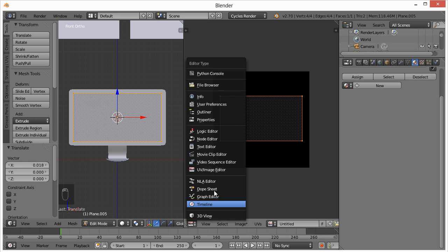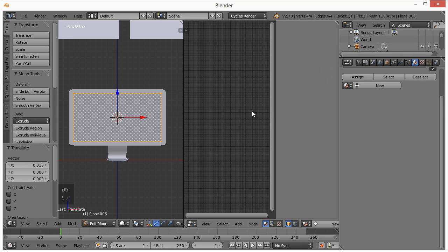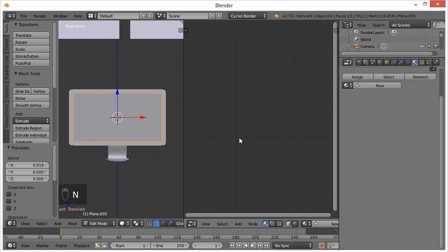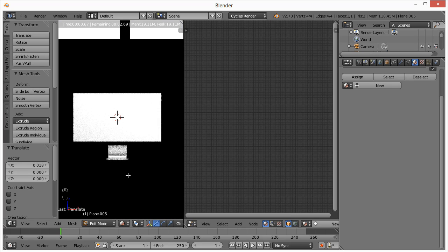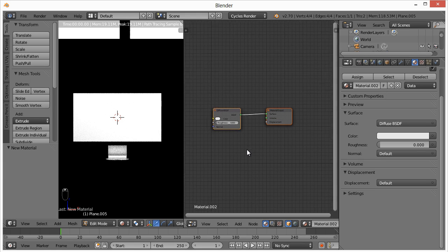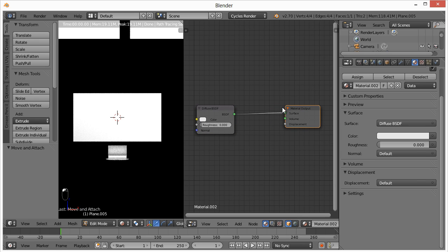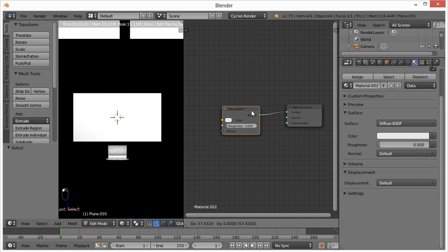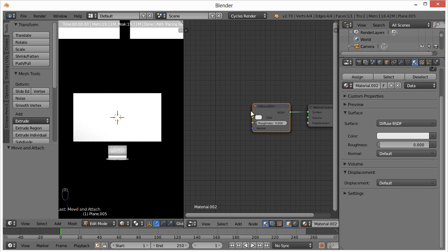I'm going to go back to Blender, and now we're going to switch back here to what's called the node editor. All right, so you'll have a blank screen there at first. And what we want to do is come over here to render just to see what everything looks like. We're in the material section, hit new, and we'll see these are what are called nodes. So we have the material output, and then we have our diffuse right here. So you can adjust materials over here or over here. Over here gives you more fine control in terms of how it looks.